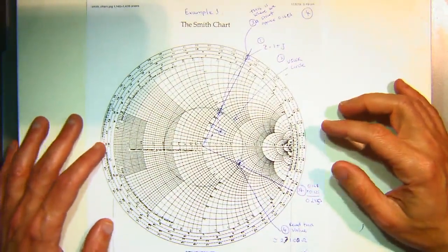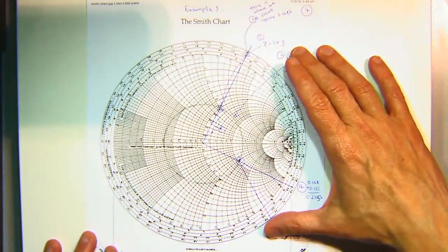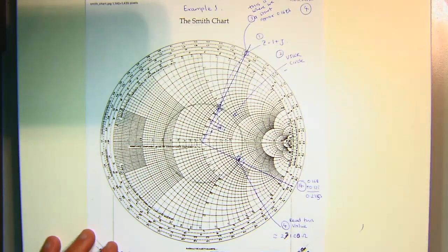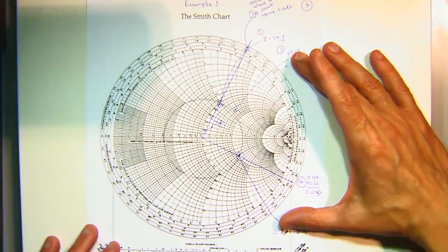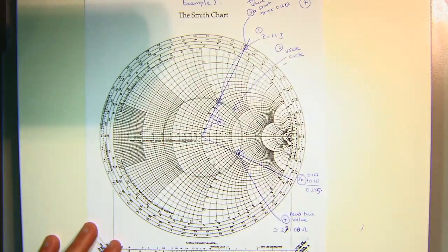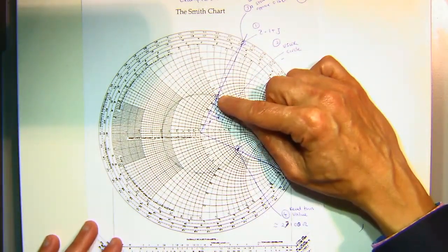So what I said was, in order to solve that specific problem using the Smith chart, and I'm hoping that you've all seen the Smith chart, I can see some faces that weren't here in the last lecture, so I don't know if you've gone through the lecture notes, but I'll go through this example again. One of the steps in order to use the Smith chart was to draw the normalized impedance on the Smith chart.